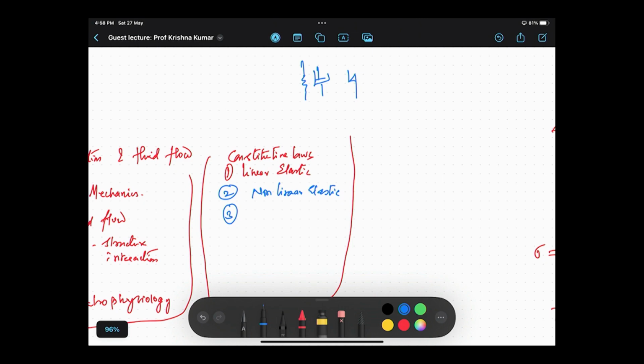If it is just a spring, only the stiffness, then that's the quantity which gives you the property. It can be linear or it can be non-linear. Purists call this non-linear as hyperelastic, governed by certain laws of thermodynamics. It's not our concern right now. It sometimes hardens. Now, we have another thing called the viscous dashpot, which actually responds to velocities. So combining these two is viscoelastic.